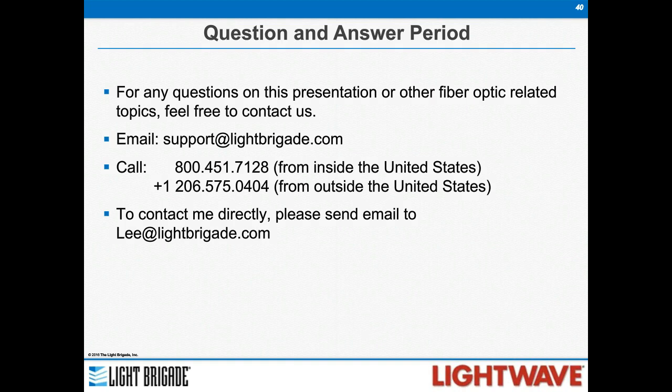Do you use the same tools to clean UPC and APC connectors, or are the tools different? They're the same tools. There are one-click cleaners, and the cassette, you can clean on the cassettes. The one-clicks, you buy the APC type so that it angles properly. The wipes and everything else work the same way. So the key with APC connectors, being angle polish, if that's specified, then you know that that network is really concerned with reflections. So just really make sure you do clean. Most products will tell you what they can be used for, so just pick a part number or a style that says works on APC connectors. But they all basically look alike.